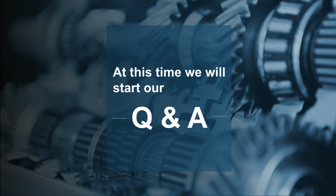Okay, great. Thank you again for that answer. Let's take a look at another question. What tooth modifications can be made to help performance? First, I want to ask everybody to use caution when looking at tooth modifications. They can be very expensive, and if you don't truly know what you're doing, it can lead to a lot of cost and not a big performance benefit. The cost is driven a lot by that when you get outside of the standards, there'll be custom tooling required, and there'll also be a custom master gear that's required for the testing, and those can add up pretty quickly.